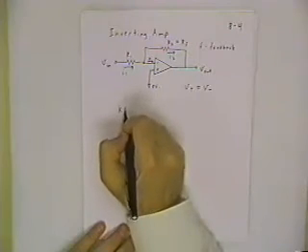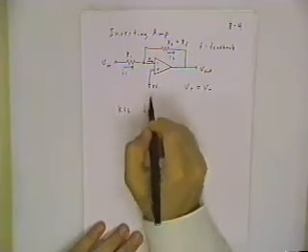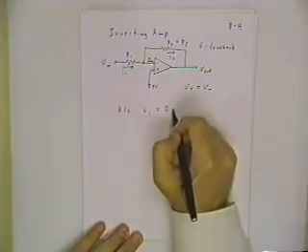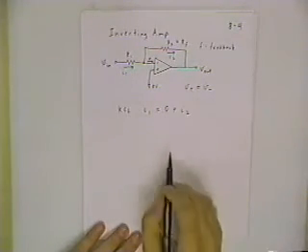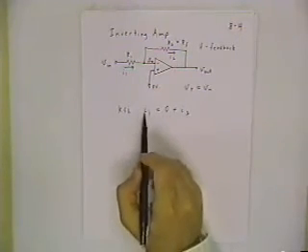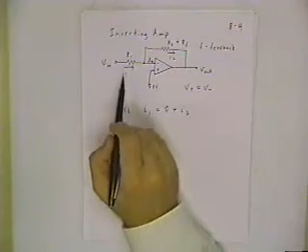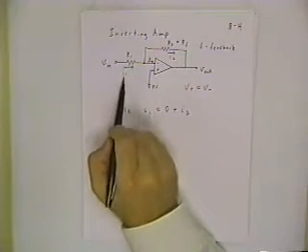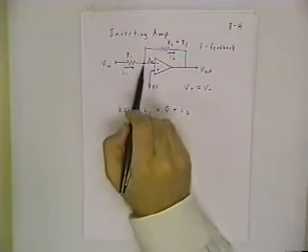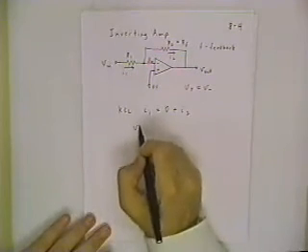So now, Kirchhoff's current law. KCL says I1 is coming in, and we have leaving 0 amps plus I2. And now we need to translate these currents into their node voltage expressions. The current I1 is going through resistor R1, and the voltages at the two ends of that resistor are Vn and 0. So let's put that in the equation.